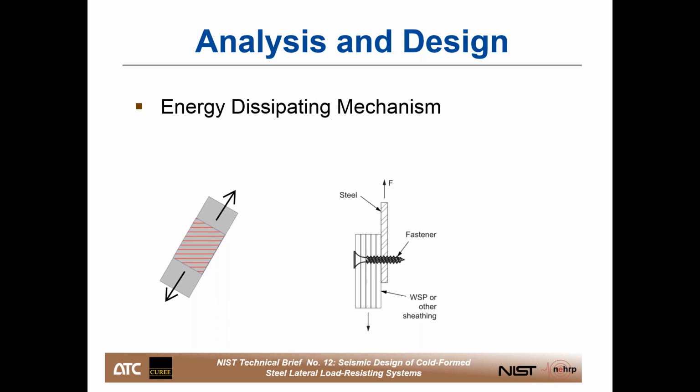So it means that all of the parts of the system did their job to deliver the forces to that strap where the energy could be effectively dissipated. Doesn't mean you might not have to replace a seismic force resisting system. Yielding still is a situation that isn't going to repair itself, but it means that things have done exactly what you intended them to do, and it's probably made the structure perform as intended.